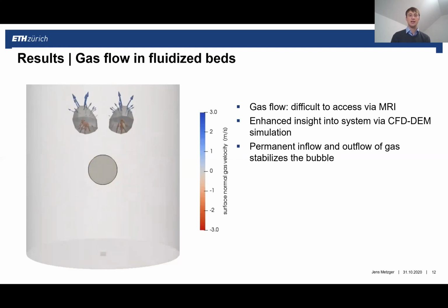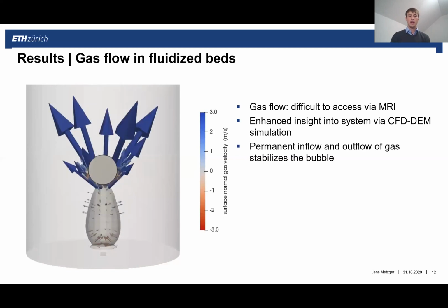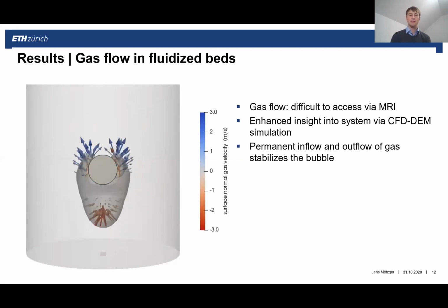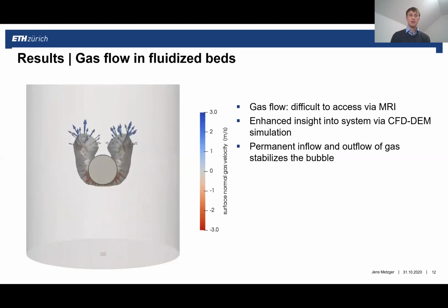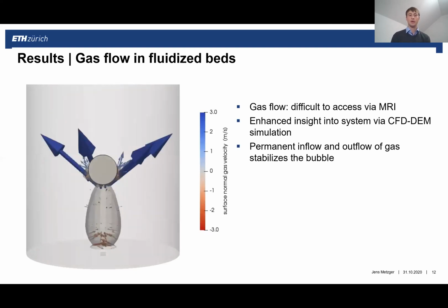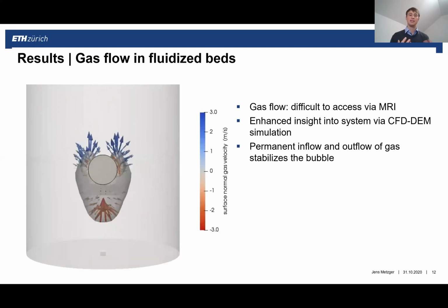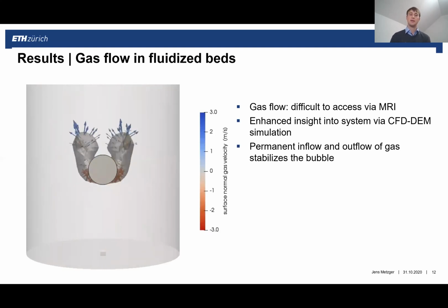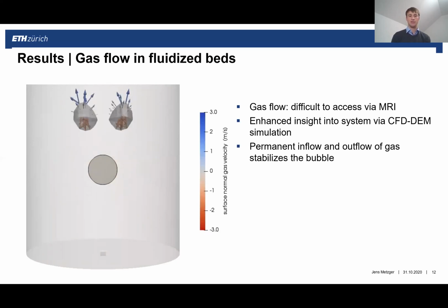We can also see here that the gas bubbles are only maintained because of a constant inflow of gas inside of the bubble. This also helps us to explain why smaller bubbles collapse faster than larger bubbles. This is because larger bubbles represent less resistance to flow than the smaller bubbles. So flow will preferentially flow through the larger bubbles and less through the smaller bubbles. So that means more flow in the larger bubbles helps them maintain, whereas less flow in the smaller bubbles makes them decay first.